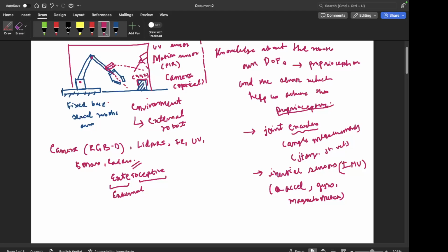The gyroscope tells about the orientation of the torso. So let's say if the robot is on an inclined surface or has toppled, and now it's in a configuration from which it should take some emergency action, right? So all this information about orientation of the robot, or any body on which the IMU is mounted, is given by the gyroscope, right? So these two pieces of information are also needed, especially by mobile robots, to function properly. Otherwise, if a mobile robot does not have an IMU, then it won't know if it's standing upright or it has fallen down, because it has no information about its orientation.